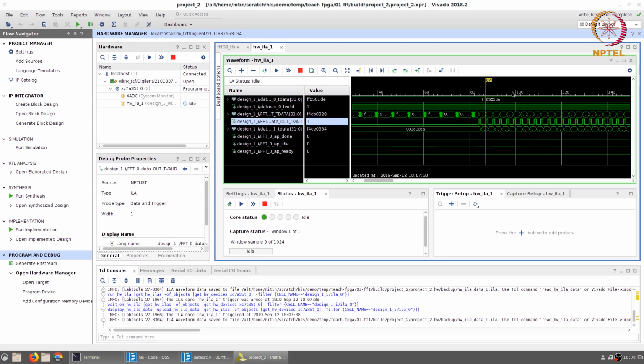So remember that you should be looking at these values only at the places where the output t-valid is equal to 1. In other words, when t-valid is 0, the values could differ by quite a large amount, but that's not consequential because the value is not valid. But whenever t-valid is equal to 1, we find that the FFT out data and the data source_1 t data match quite closely, well within the tolerance limits that we had set.